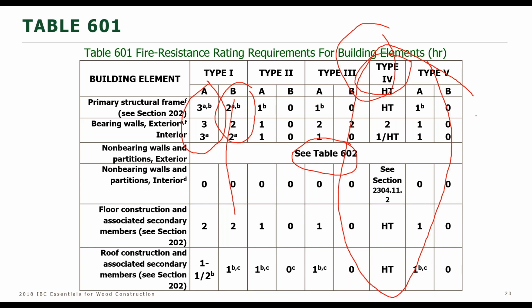Now we're going to have heavy timber walls, solid timber floors, for instance, heavy timber columns, and in many cases walls. And they're going to be rated, and they're also going to have a minimum requirement for non-combustible protection, such as by gypsum. And this is the first time that we are going to have building elements that require both a rating as well as a minimum cover by non-combustible protection.